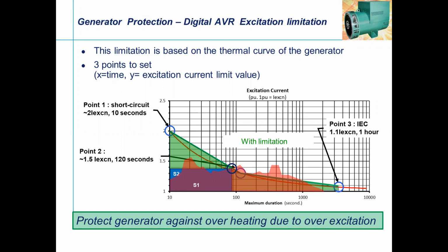My excitation will remove the powering to the exciter, so the voltage collapses and the generator will be out of the system. That protects the generator from over excitation, even though the demand has come to that. Of course, failures can happen with improper settings. This is where experts like the manufacturer come into play. A good commissioning engineer comes into play.